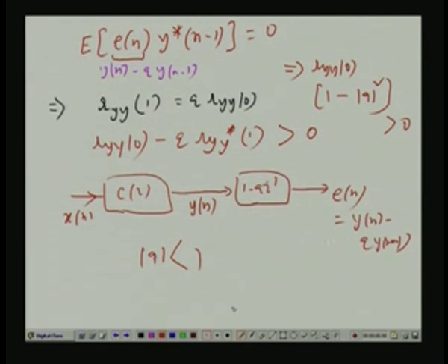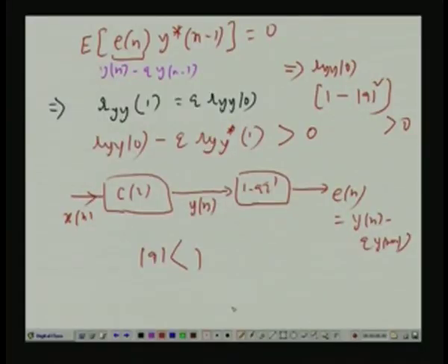So, this I did only for one root, I took out one root. I took out that factor 1 minus q z inverse separately, and the rest of them I put under another polynomial C z. Now, I can go on doing it to each and every root. This only proves that every root of that polynomial is within the unit circle. So, provided you provide accurate estimates of the autocorrelation values in the Yule-Walker equation, you get this. Okay. So, it guarantees the stability and causality of the AR model. So, that is all for AR modeling.